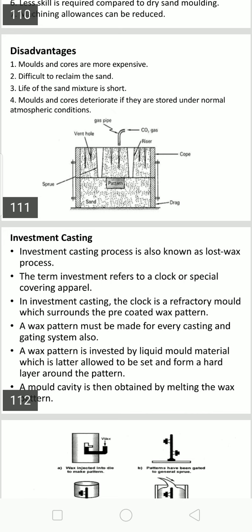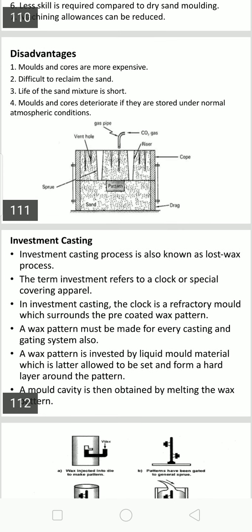And precision casting: highly precise casting with a highly finished surface, and very small to medium castings can be produced, hence the name precision casting process. So all these terms are applicable to only one process. In this process, disposable or expendable patterns are used, as I said, so those are all wax patterns. This is suitable for production of precision parts.